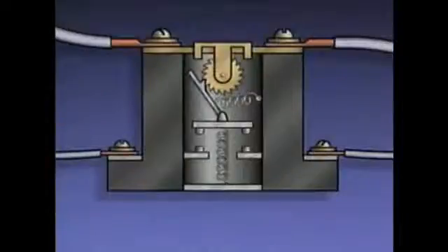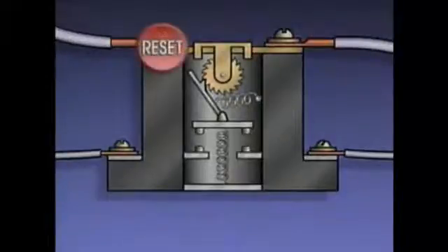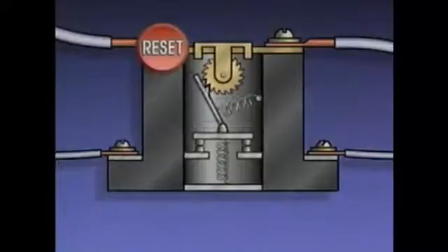When the current in the power circuit stops flowing through the heater, the heater stops generating heat. When the heater stops generating heat, the solder then cools and becomes solid again. When a reset button is pushed, the contacts of the overload device close, which makes it possible to restart the motor by supplying current to the M-coil.